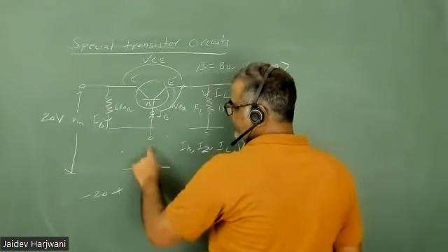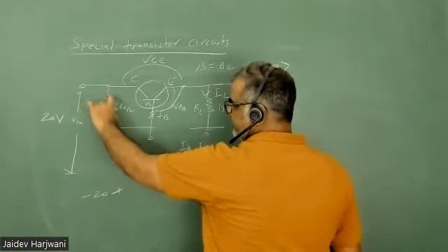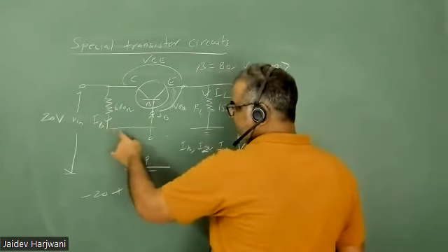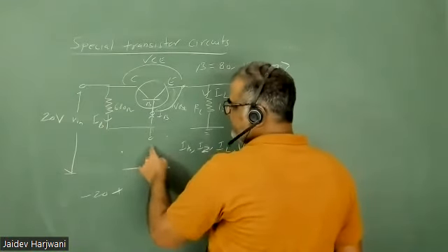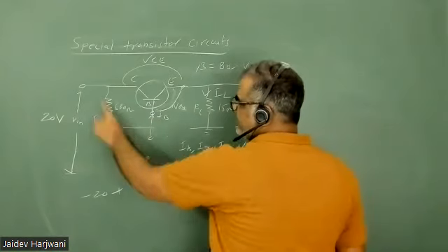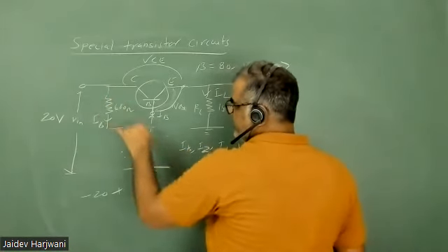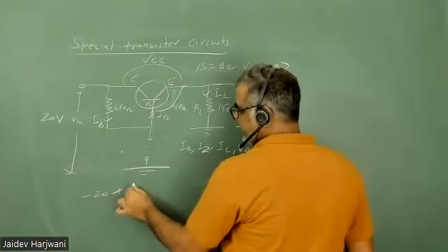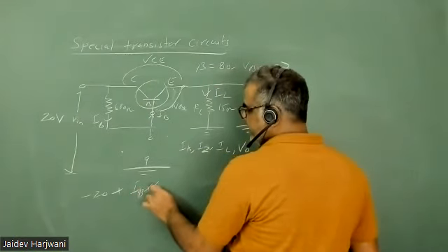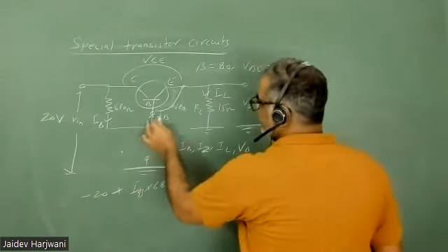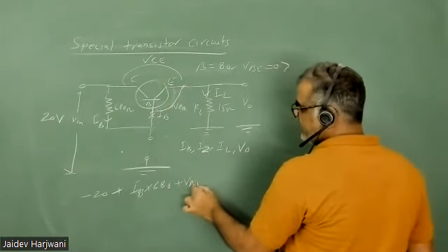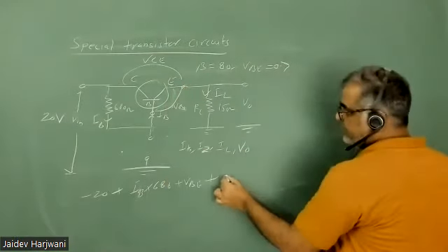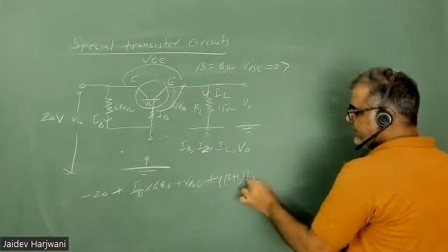As soon as this is open, this current will reduce, and once this current reduces, this voltage will automatically increase. Because otherwise the current is IB plus IZ, in milliampere. But now you remove this one, so now current is only going here. This whole current becomes IB, and the voltage drop here will reduce, and you get high voltage here. So now it is minus 20, and then you have IB into 680 ohm. Okay, and then you go from here. This is your VBE. And then here this current is IE. IE means your (beta plus 1) IB, equals to 0.